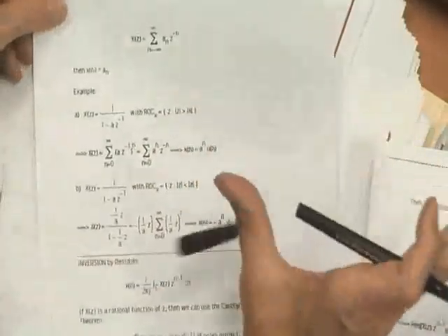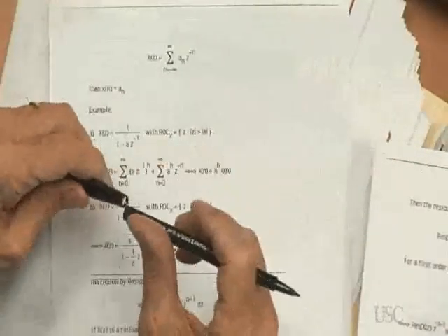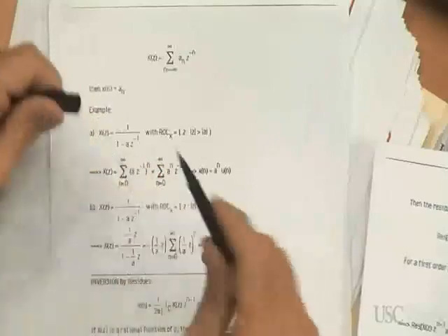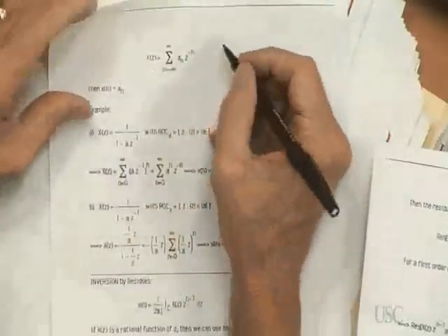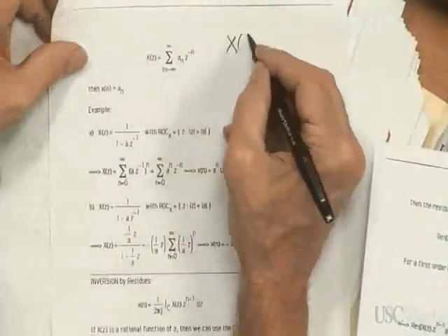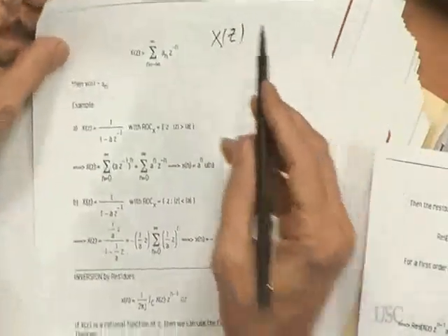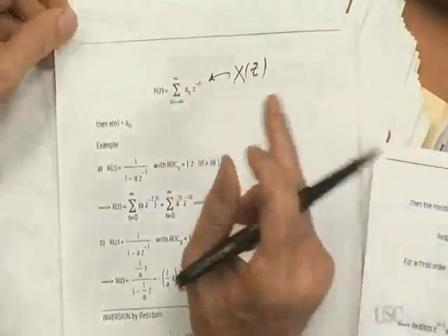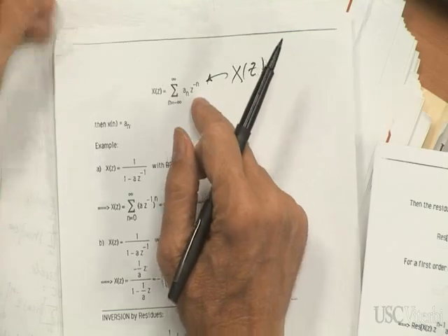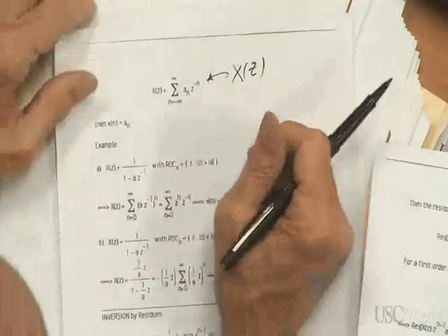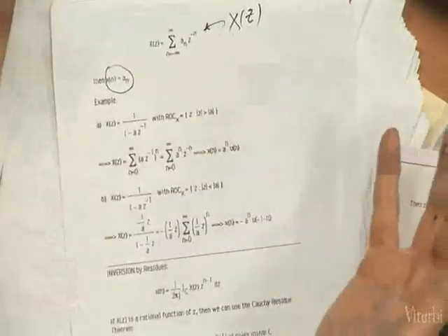But to give you a little insight, one way to do an inverse Z transform: if I give you a Z transform X of z, plus the ROC, of course, and I can expand X of z in a power expansion of z, involving both positive and negative powers of z, then done. I can just read off x of n directly from the coefficients by definition.